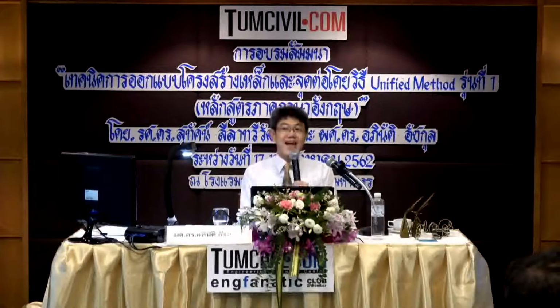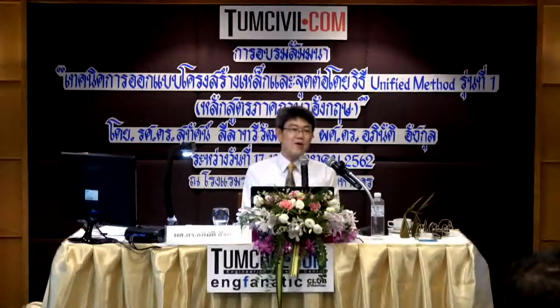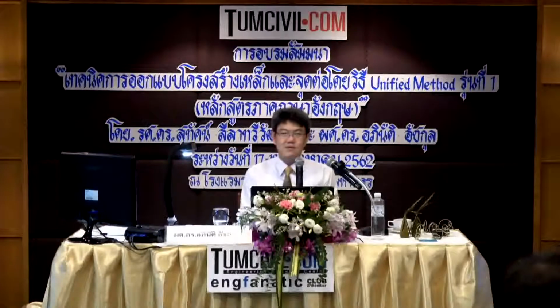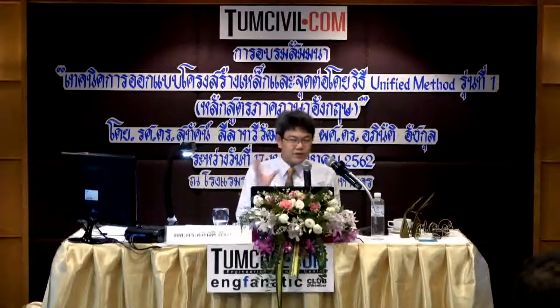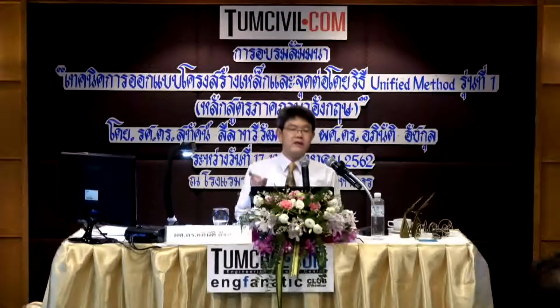Because it will not happen, right? How can tension cause buckling? Not on this planet. But compression causes buckling. So that means when you are dealing with the beam, you need to brace the beam where compression is.